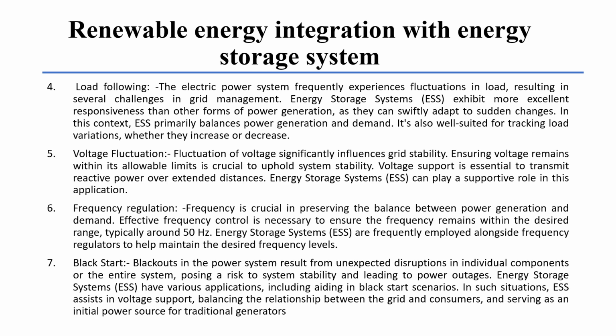The fourth one is load following. The electrical power system frequently experiences fluctuations in load, resulting in severe challenges in grid management. Energy storage systems are more responsive than other forms of power generation as they can swiftly adapt to sudden changes. In this context, ESS primarily balances power generation and demand. It is also well suited for tracking load variation, whether they increase or decrease.